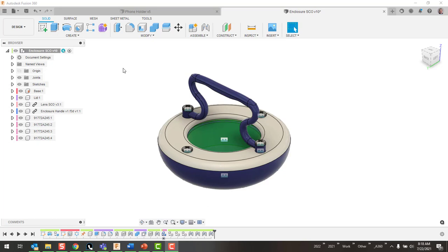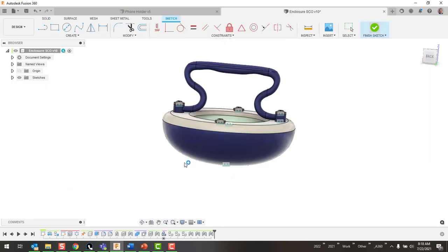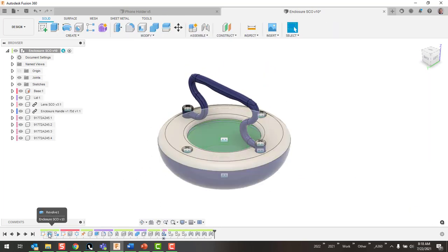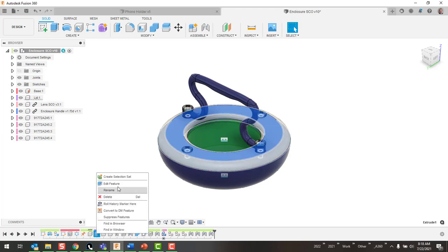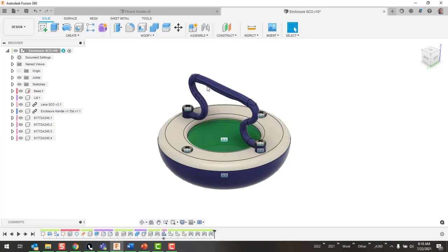We could do an overview presentation where we do something like this, where we just do 3D CAD, where we start with essentially a 2D sketch of a shape. We revolve it to create that bowl shape at the bottom. We add a lens to it. We also add a lid to the part. We bring in a handle that is already pre-done that was modeled up somewhere else. And then we also connect to McMaster-Carr to bring these screws in.